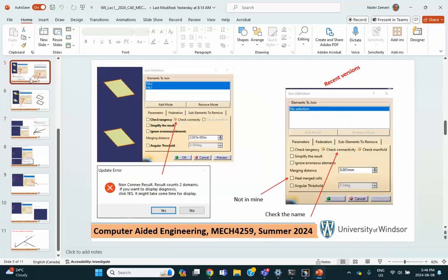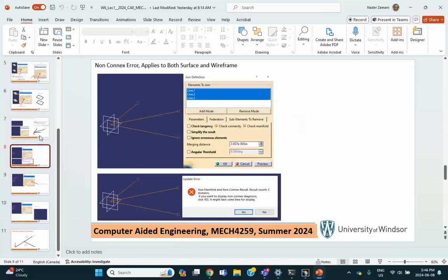So the moral of the story is when you get messages like this for surfaces or for beams, you have to worry about these two checkboxes, okay? And hopefully if you uncheck it, then it's going to work, and it will, unless there's something else that's wrong. So that takes care of this tutorial for today. And remember, on Thursday, I will do a review in the sense that we'll do some problems, and hopefully it's okay with you. You can do it too.